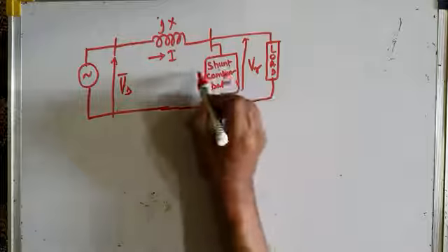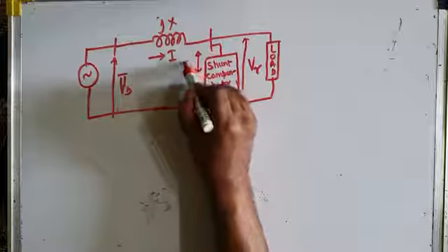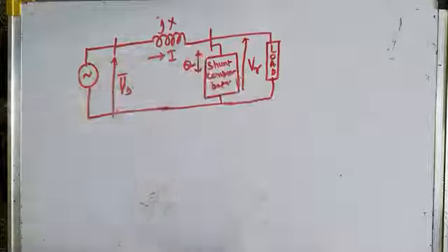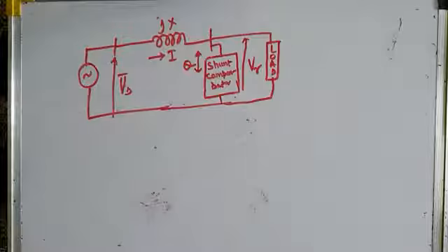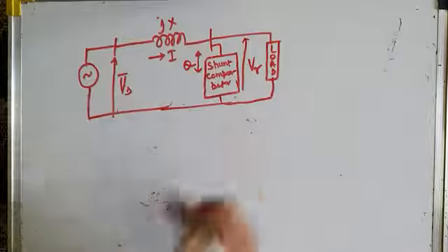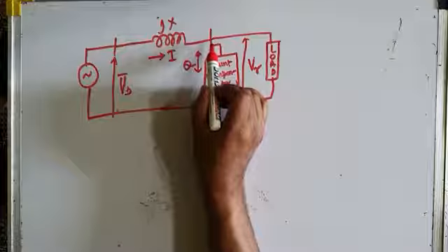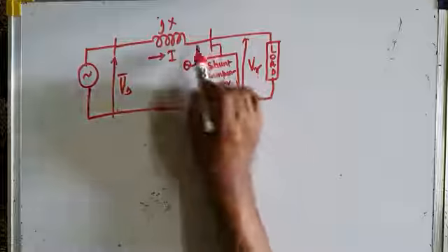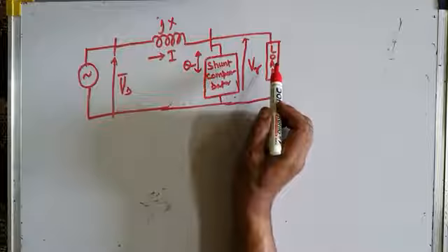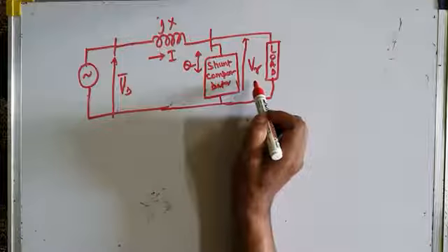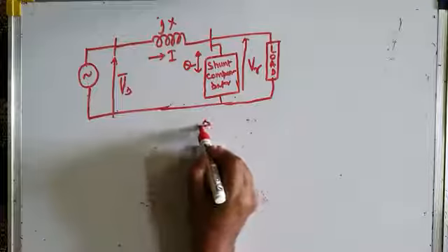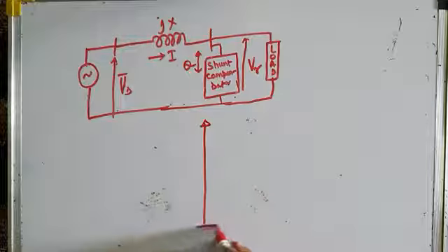Now what will this shunt compensator do? It will absorb or generate reactive power and inject that reactive power into the bus, and it will improve the receiving end voltage. By injecting the reactive power into the bus, into the system, it will provide voltage support, and hence it will improve the voltage stability. Let us try to understand that with the help of graphs.